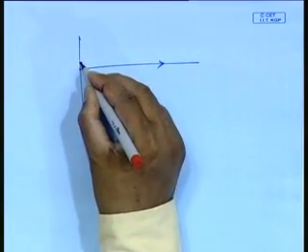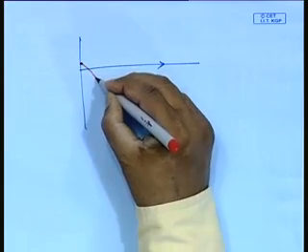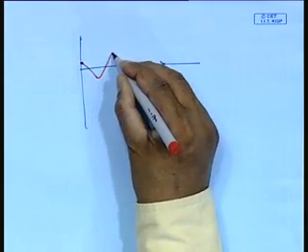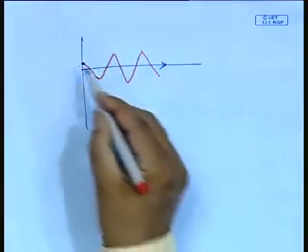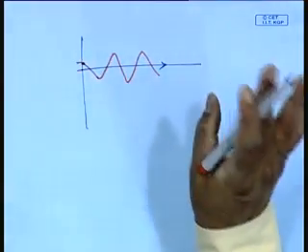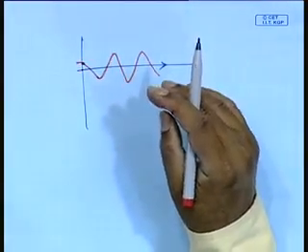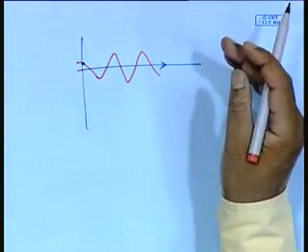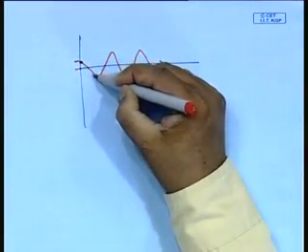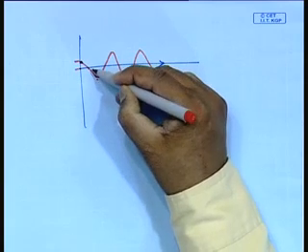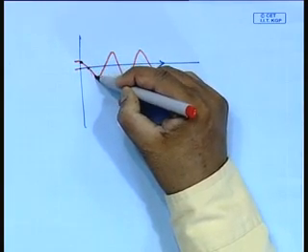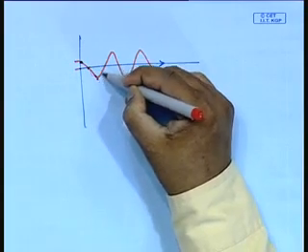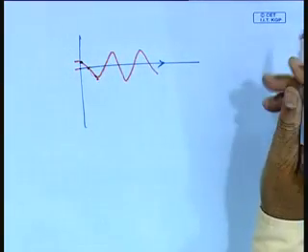So when I give that, it tries to overshoot, and then I correct it, it overshoots again. Basically it tends to oscillate like that, because let's say I am having an error of plus 2 degrees. Immediately I give a rudder on the other side, so the rudder makes it go to the other side. But by the time I come here and want to turn it back, it has overshot somewhere here. Then again I turn it. So it tends to have some kind of oscillating behavior.